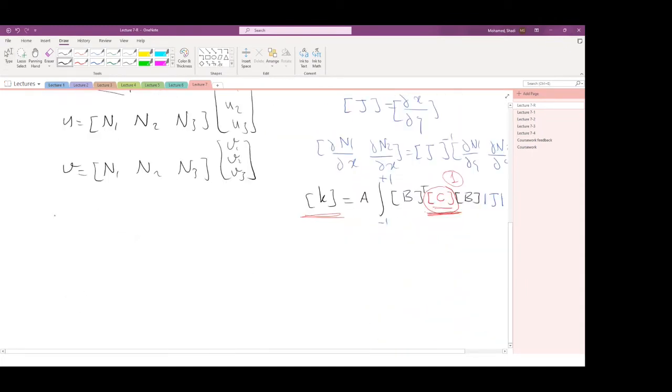Now, usually it is possible to write U and V in the same matrix because we have a single matrix for displacement in the one dimension. We also want to have a single displacement matrix for the two dimensions. So I'm just going to rewrite these two equations here as a single equation, using matrix notation. So U and V as a vector would be equal to, I'm just going to rearrange this so that I can pick the components that I need, and the components I don't need are going to end up being 0. So I have N1, 0, N2, 0, and N3, 0.